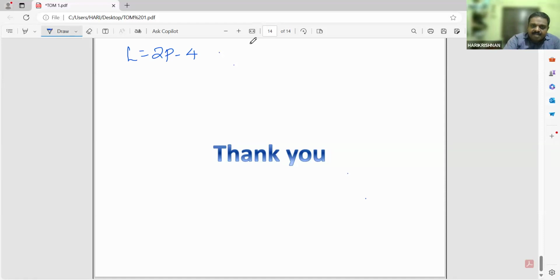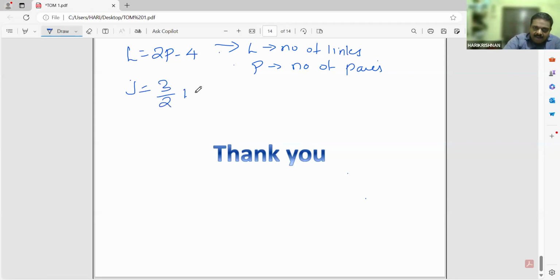L is the number of links and P is the number of pairs. Then there is another equation: J is equal to 3 by 2 L minus 2, in which J is the number of joints. So L is equal to 2P minus 4, where L is the number of links and P is the number of pairs. Similarly, J is equal to 3 by 2 L minus 2, where J is the number of joints. So first is the relation between the number of links and pairs. Second is the relation between the number of joints and links.